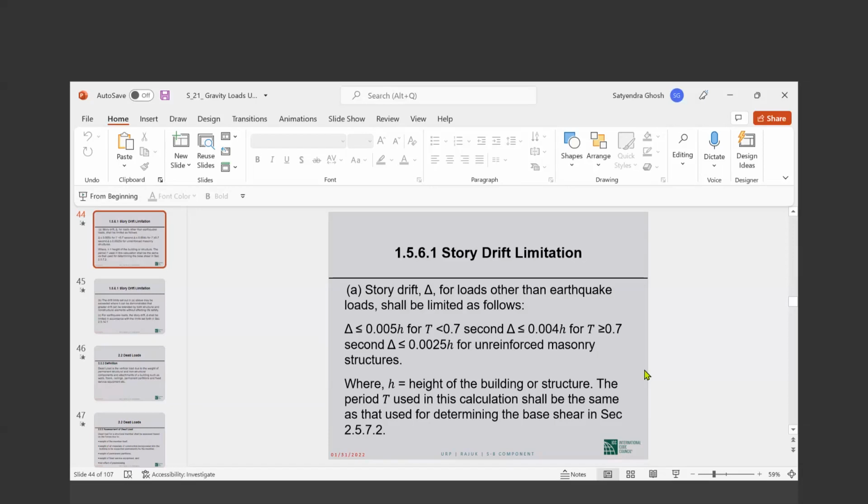Can we use live load reduction for footings and foundations? I do not know that anywhere we are told not to. Whatever we have taken for the superstructure is carried down to the foundation. So you just have to design for that.